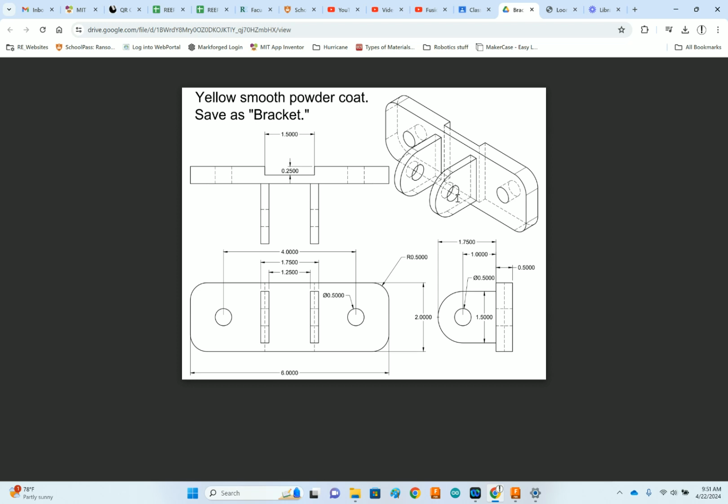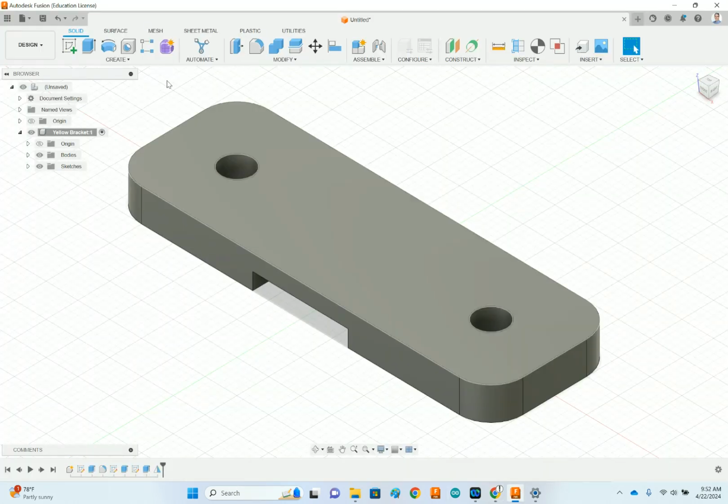I'm going to round it off with a hole in it. Then I'm going to come back and cut the middle out of it. I'm going to make it as one big chunky rounded over thing and then come back and cut the middle out. So it's 1.5 by 1.75 is a rectangle we're going to draw on that face. And then we're going to extrude it upward 1.75 tall. 1.75 by 1.5. So let's go into Fusion.